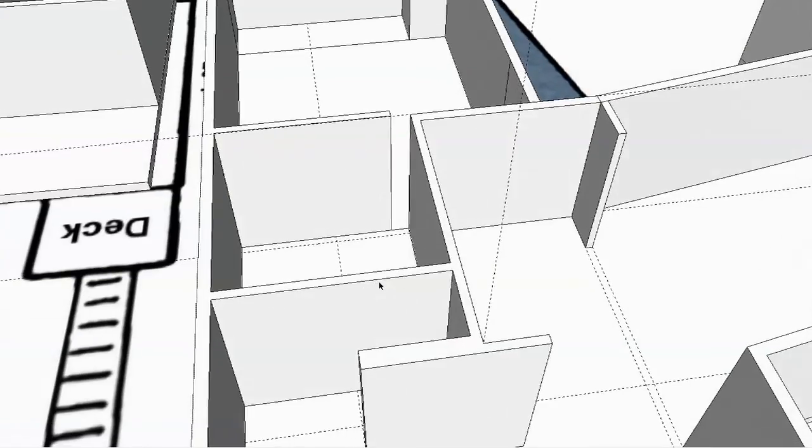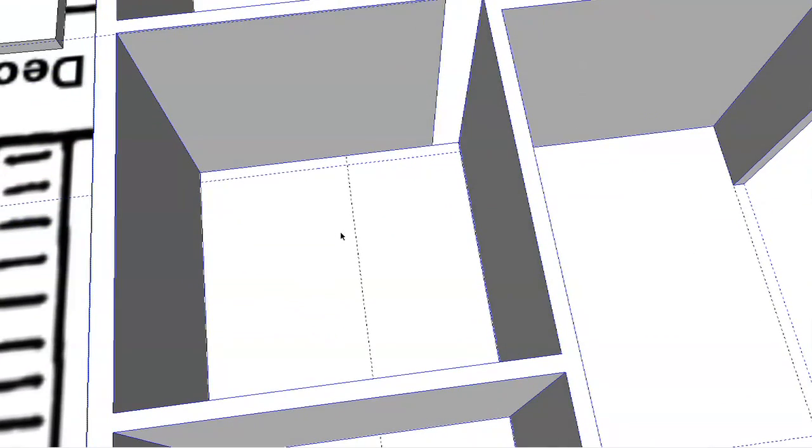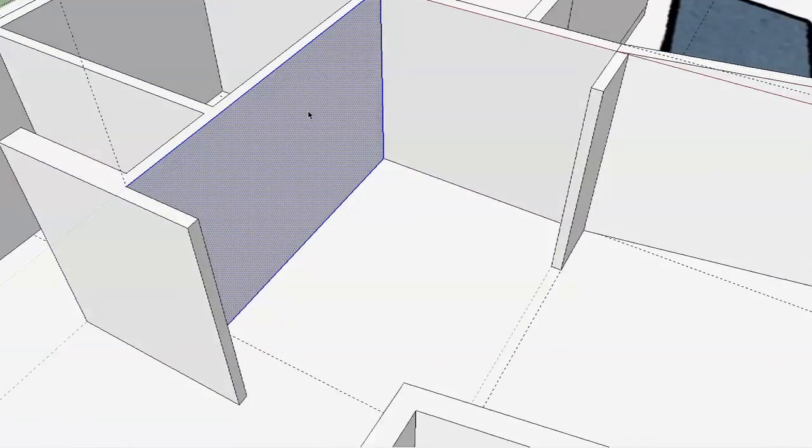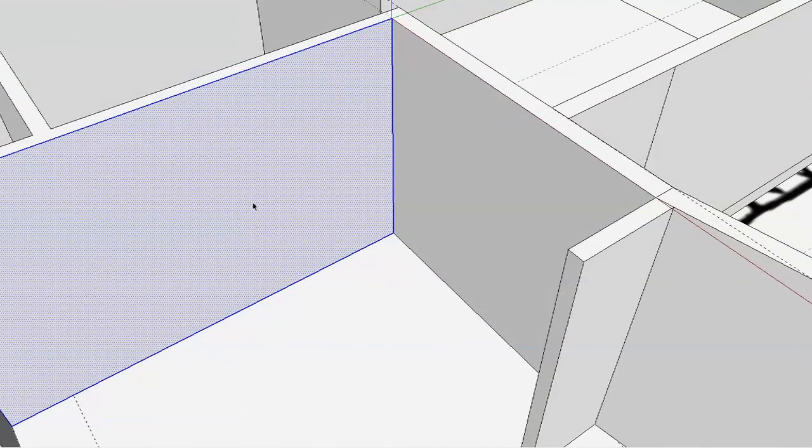But are the bathroom dimensions correct yet? Are they actually correct? Well, let's take a quick look at that. The fact of the matter is that this bathroom is still too wide. Now, why is that? This is something that requires a little bit of thought, and you actually need to put on your engineering hat for a second, because if you look at this wall right here, this is where our fridge is going to be. And this is where our oven is going to be. And all these appliances need extra things behind them. The fridge needs a water supply. The oven needs one heck of a power supply. You can't fit that in a standard 4.5-inch wall.